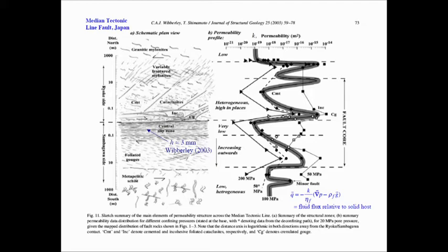And look at the 50 MPa data, where you read the permeability up here. What the two curves indicate is that it depends on whether you got to 50 MPa by first, for example, compressing to 200 MPa and then unloading, or whether you got to 50 MPa by just the original load rise. So it's irreversible, and anyone who's looked at the loading of soil materials will understand that kind of consolidation behavior.